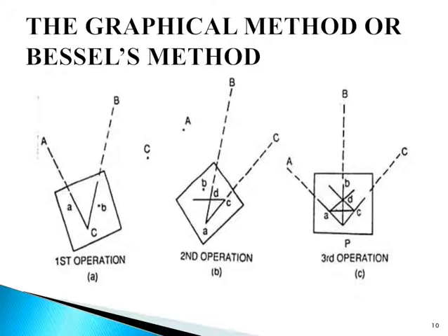So the alidade is placed along line DB, here is line DB, and point B is bisected. At this position, the table is said to be perfectly oriented. Now the rays from capital A and small a, capital B and small b, capital C and small c are drawn. So all the rays are drawn.